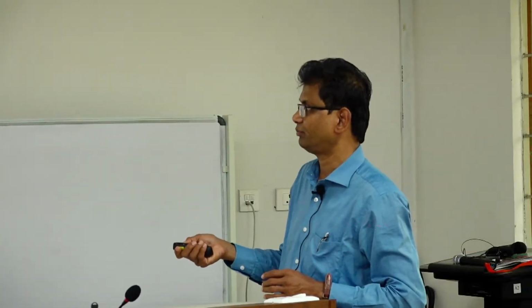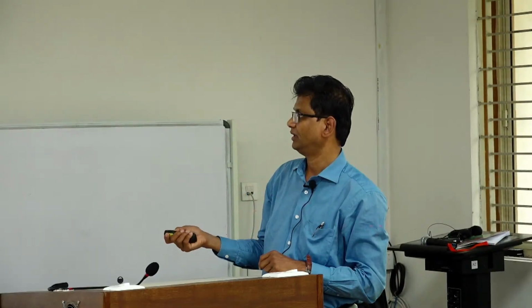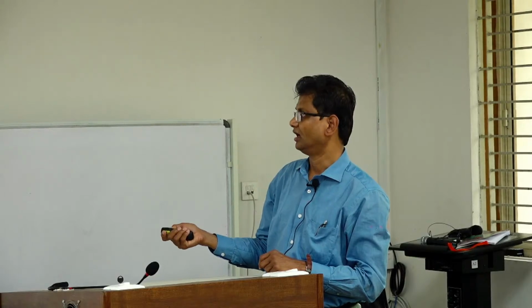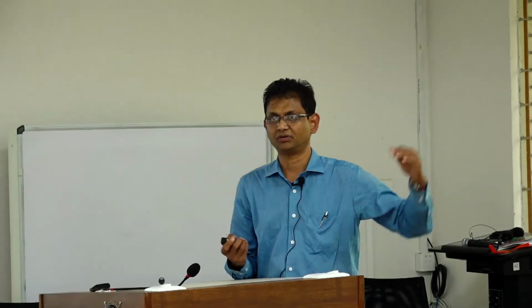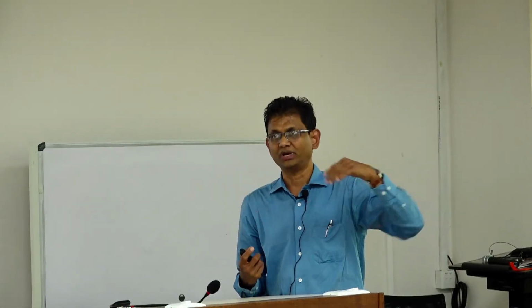What is 1.5 AM? It is the power we get when the sunlight is at a zenith angle of 48.2 degrees, which is around 1.5. How do you calculate it? The simple equation is AM equal to 1 by cos theta. If you put 48.2 in cos theta, 1 by cos 48.2, we can calculate this 1.5. If the sun is straight overhead, at 0 degrees, cos 0 is 1, then the AM will be 1. AM 1 means the sun is exactly overhead. Normally we take sun radiation at 48.2 degrees, and in that condition it is 1000 watts per meter square.